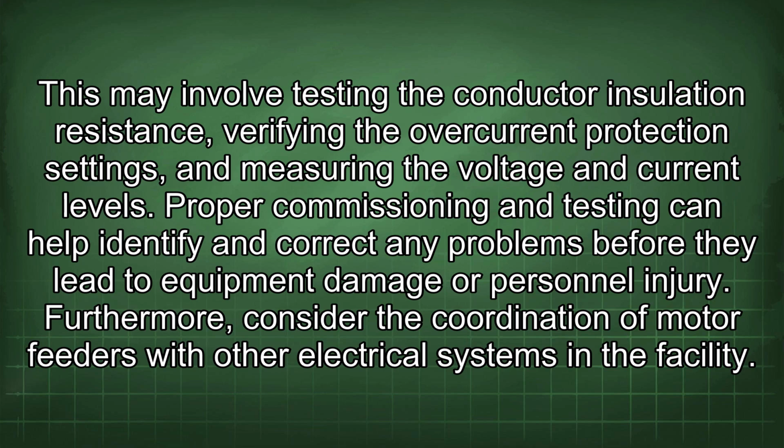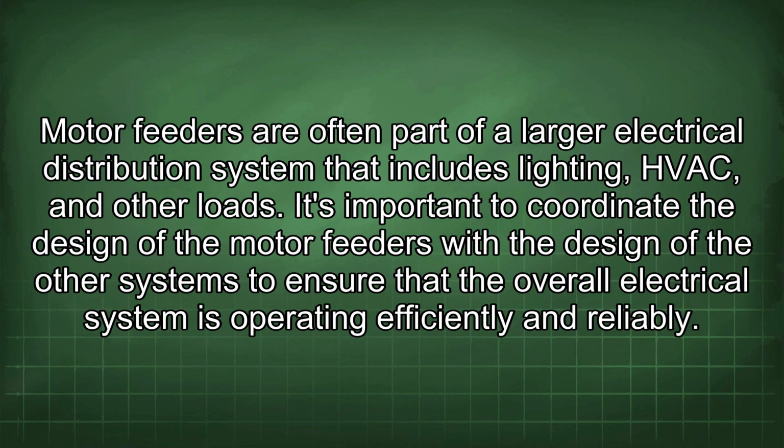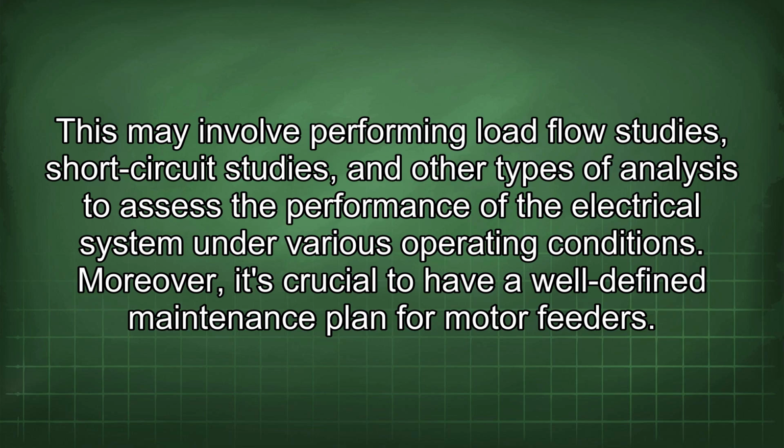damage or personnel injury. Furthermore, consider the coordination of motor feeders with other electrical systems in the facility. Motor feeders are often part of a larger electrical distribution system that includes lighting, HVAC, and other loads. It's important to coordinate the design of the motor feeders with the design of the other systems to ensure that the overall electrical system is operating efficiently and reliably. This may involve performing load flow studies, short circuit studies, and other types of analysis to assess the performance of the electrical system under various operating conditions.